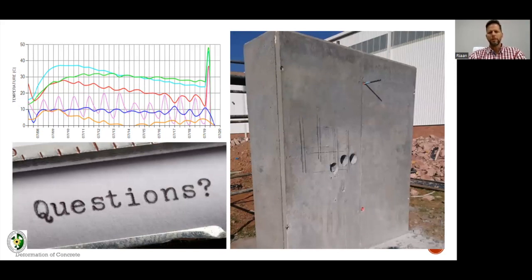I agree. Yes, you can design for heat of hydration with reinforcement, but I would say that is your ultimate fail-safe, if you've explored all the other options. It is better to prevent it than to try and arrest it. That's my opinion.